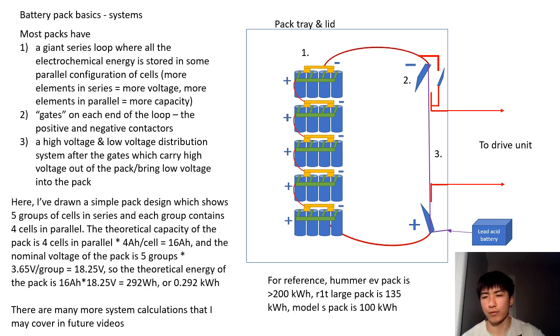So if the requirements are flowing down from the customer or from leadership, like we need to build a vehicle that has a super fast 0 to 60 time, then you might want to consider something that has very high voltage, right? So you may be putting more things in series. Whereas if leadership is telling you, oh, we want to make a very low cost, high range vehicle, now you have to start thinking about having more things in parallel